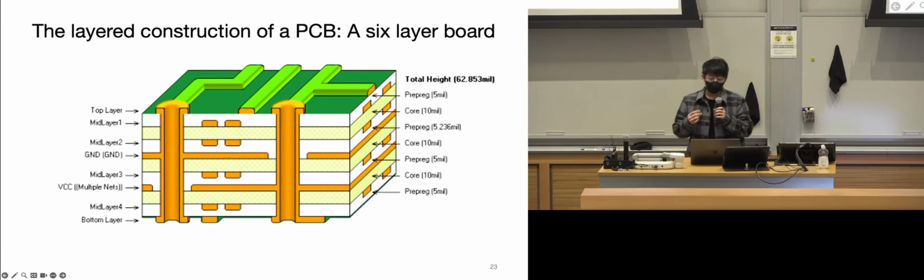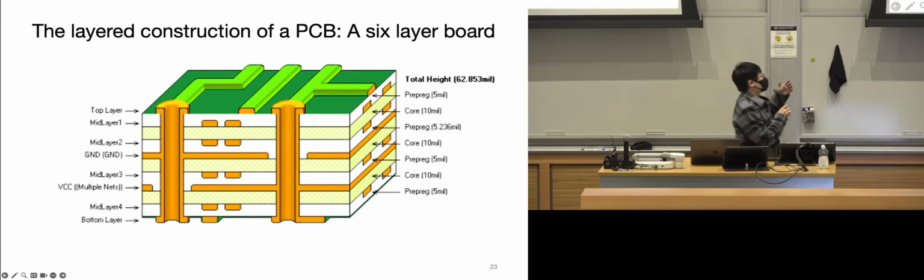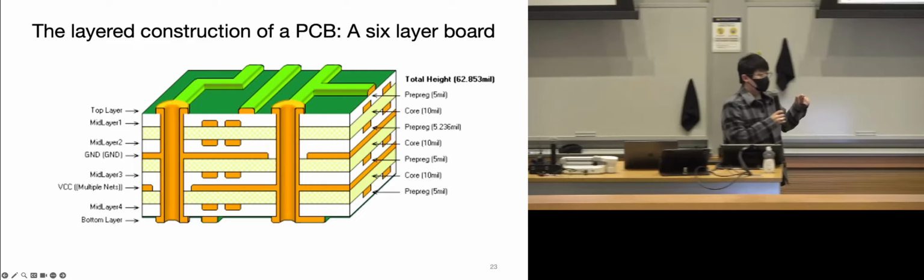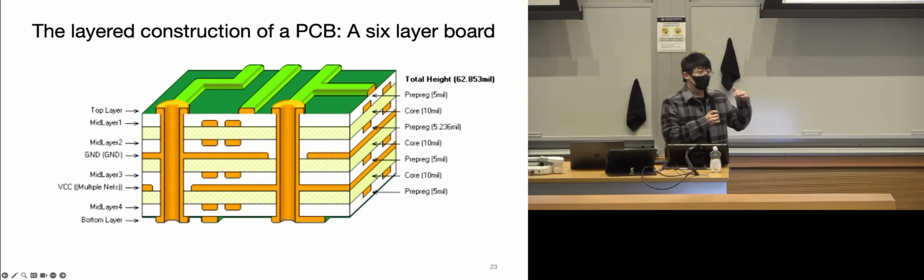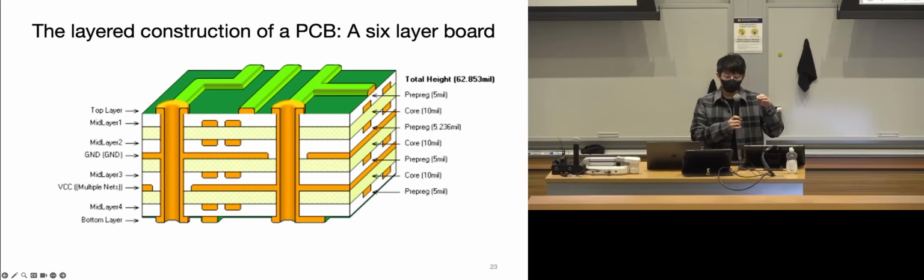So if you have, say, a MacBook, you will notice, not sure if you did, that the entire case of this computer is actually ground, the metal piece, just to make it less prone to the environmental noise. The layers that are not the ground and VCC planes are usually used as additional space to put your wires.